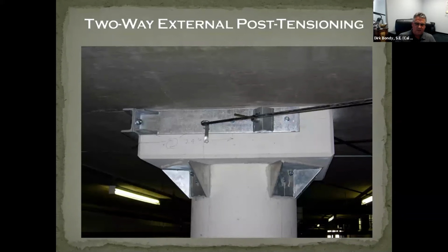And this is how we had to get through the column caps. Notice everything is galvanized. The tendons are galvanized. We galvanize all the hardware. We don't want to create another problem that in 10 or 15 years has a corrosion problem itself. And you'll notice we can't help ourselves. We're always strengthening the punching shear. That to me terrifies me. After 1994 and walking that job with my father, I'm terrified of punching shear failures on anything that I work on, so we're always strengthening that.